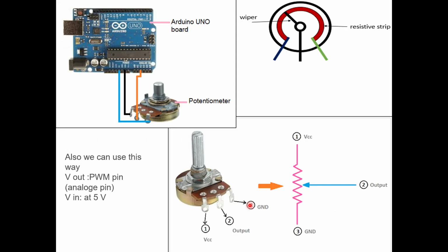So what is happening when you rotate the knob? You see there are three pins here, one pin, two pin, and three pin. What is happening is the one end and this second end, blue and green end, are connected with the resistance wire. And this black wire is called the wiper wire. This is actually increasing the length of your resistance. As of now, from here, the pointer where the wiper is, to the left side towards the blue side, that is the length of your resistance.